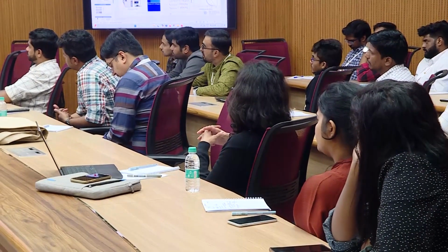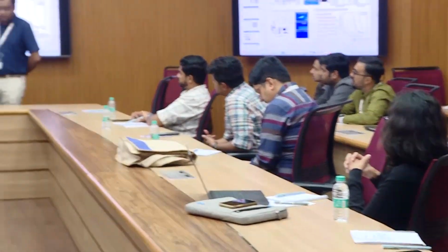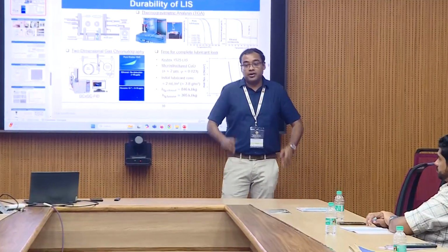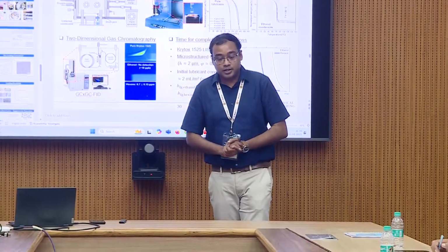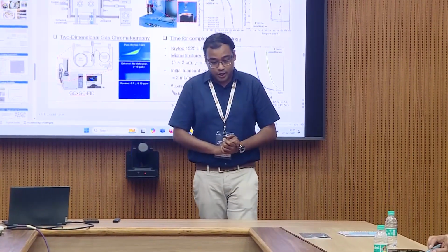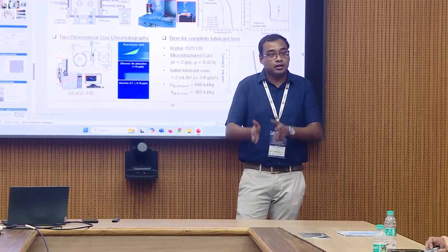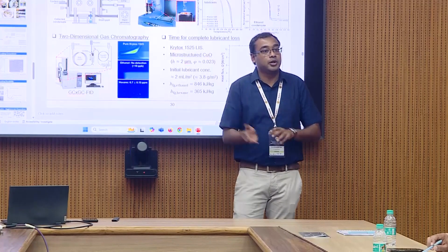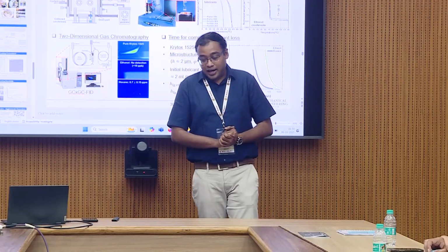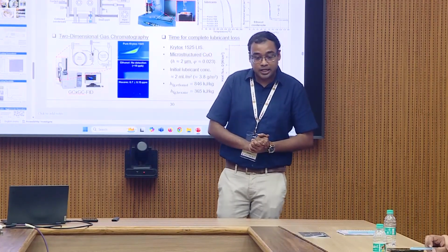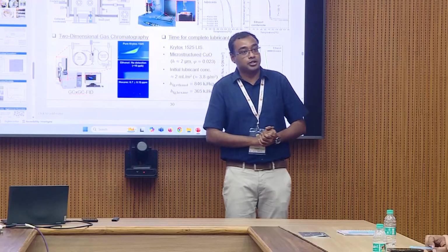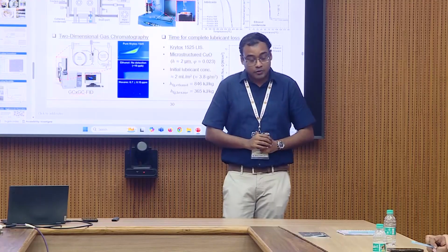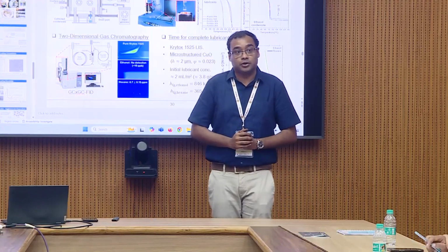Yeah, so the heat transfer did not degrade over a period of close to 7 months. And the reason it ended up being 7 months is that this was back at UIUC. We were testing, and then there was an outbreak of COVID. So everything was shut down, and we went home, and the experiment kept on running on its own. And when we came back after 6 or 7 months, it was still showing dropwise condensation. So we did the measurement of the heat transfer coefficient, and there was no degradation of the heat transfer coefficient.